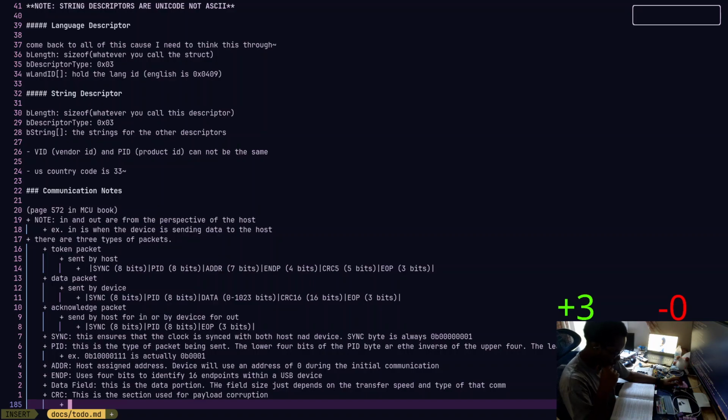First, the data bits to be protected are treated as a binary number. Second, we divide the binary number by another predefined binary number. Finally, we select the remainder of the division as a CRC code. The receiver performs the same steps to compare the remainder calculated and the rest received.